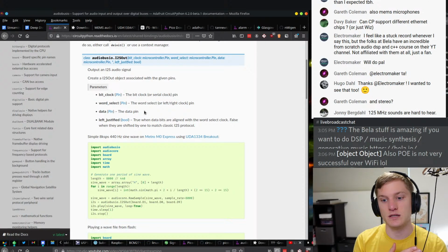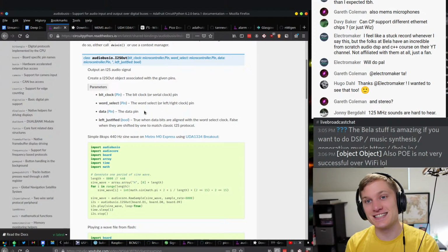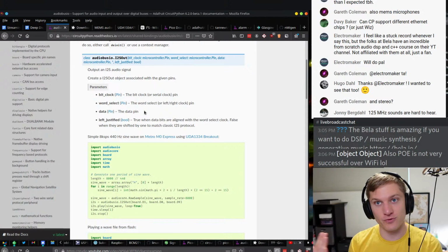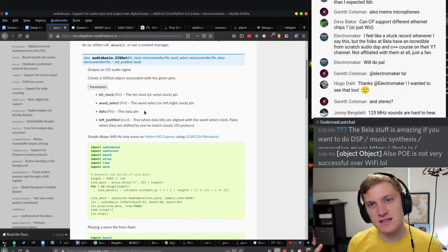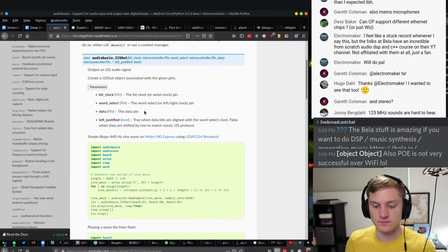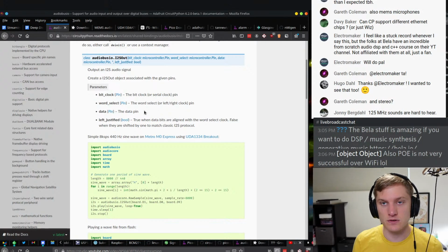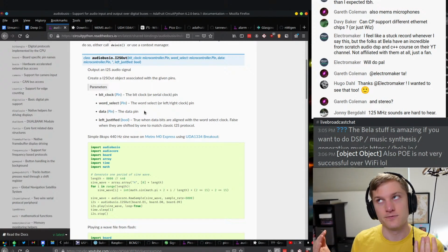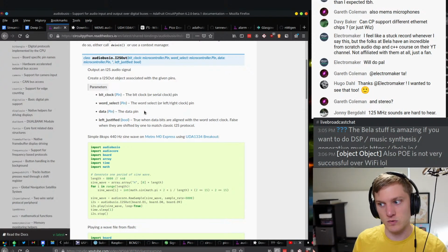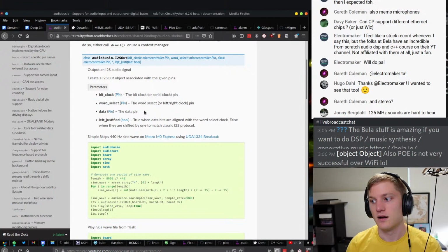So that means that we need to deliver one sample at 44.1 kilohertz, which is kind of the standard because that's what CDs are. And you can actually queue up stuff. The PIO has a 4 entry buffer, but if you're only doing one direction, you can use the other one and make it 8. So that gives you some flexibility there.